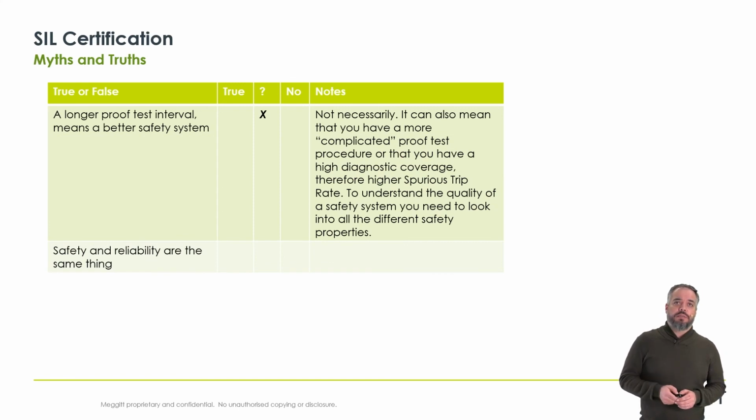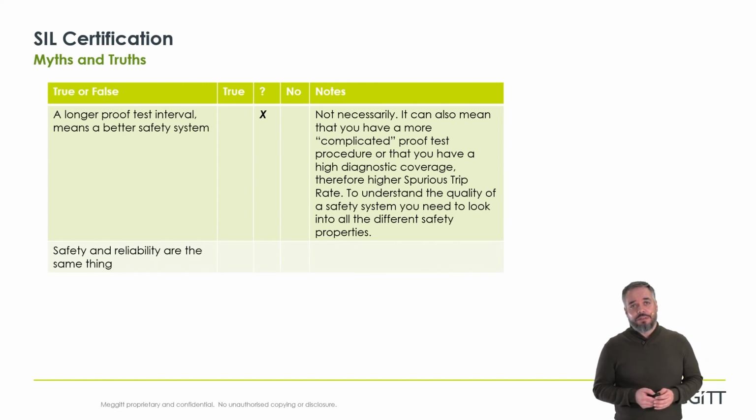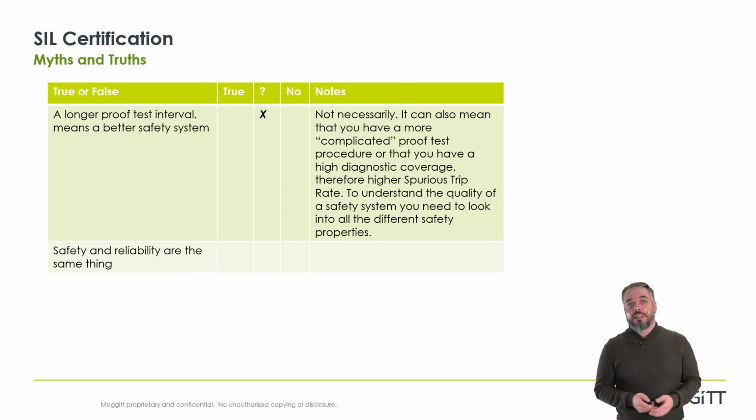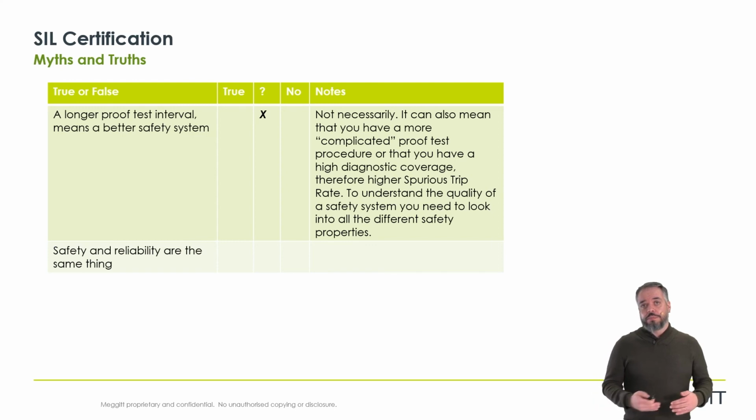Are safety and reliability the same thing? It depends a lot on what you mean by reliability, but a system can be safe and not reliable. For instance, it can have a lot of spurious trip faults, but it will always fall into a safe state, so it's safe, but it's certainly not reliable. On the other hand, a system with very low diagnostics will be more reliable, but less safe.